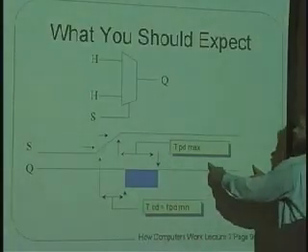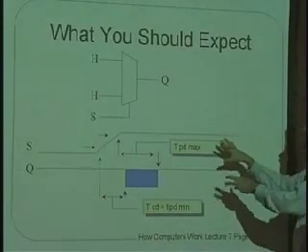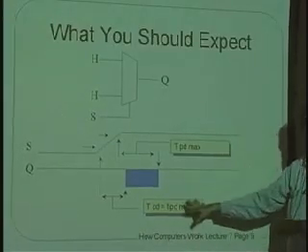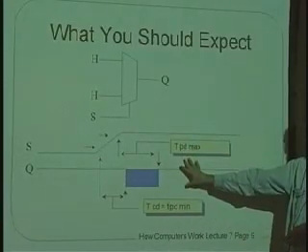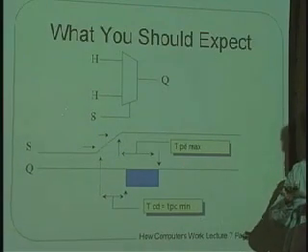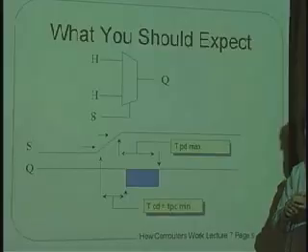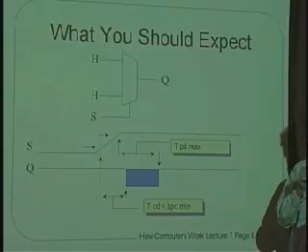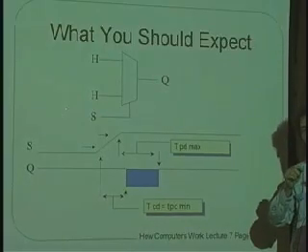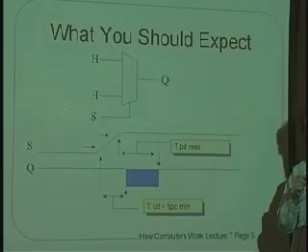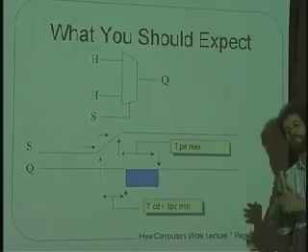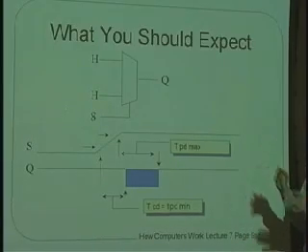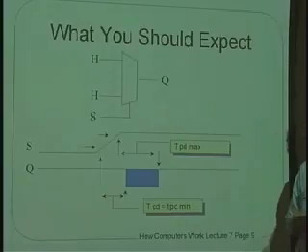There is no relationship in this picture here that says TPD max is more than TPD min. Nothing in this picture proves that. Okay? I'm telling you that in general, TPD max is bigger than TPD min. Would it be less than TPD min? Because we've inserted this difference between valid and invalid, according to that definition, one could imagine a circuit in which that were true. In truth, there are no circuits like that. But from what you guys know so far, there's no reason to believe that the max should be bigger than the min. Except that it is. And you'll see why later.